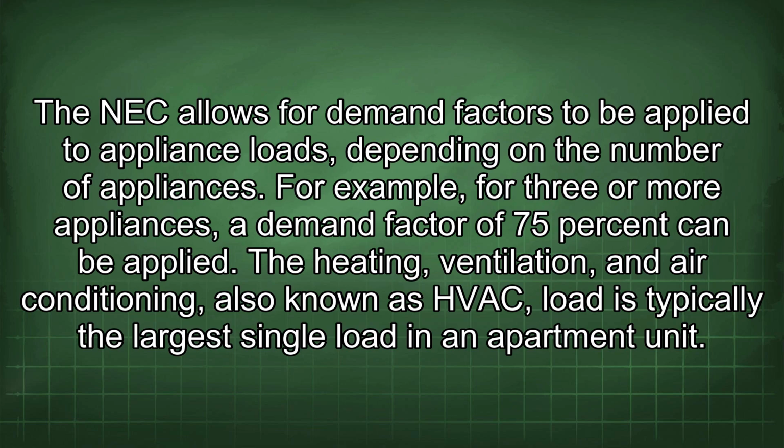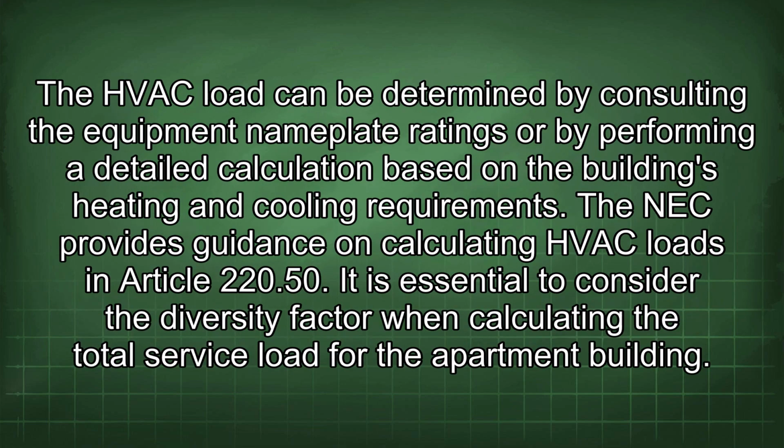The heating, ventilation, and air conditioning, also known as HVAC load, is typically the largest single load in an apartment unit. The HVAC load can be determined by consulting the equipment nameplate ratings or by performing a detailed calculation based on the building's heating and cooling requirements. The NEC provides guidance on calculating HVAC loads in Article 220.50.